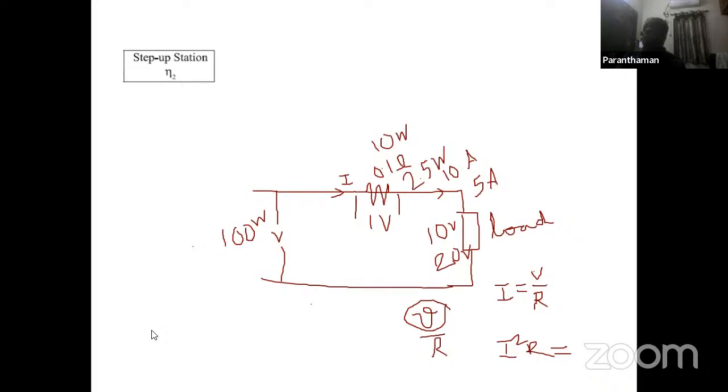Correct, sir? That peak hour demand, if we can distribute it to non-peak hours, we need not build a 1,000 megawatt power plant for another 10 years. That's why the maximum demand levy is imposed. It's a part of demand side management.